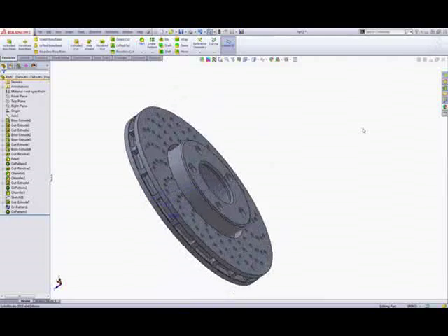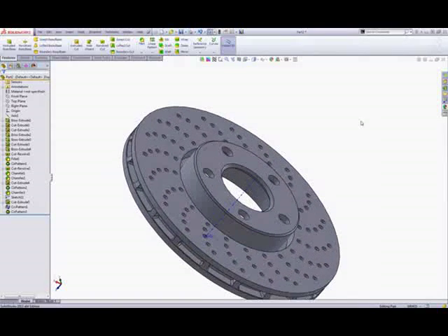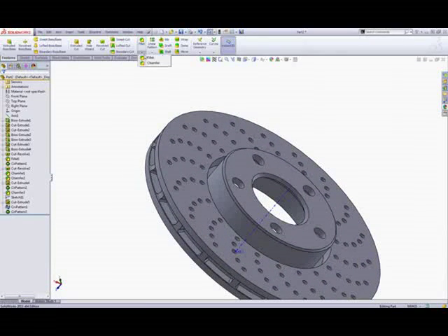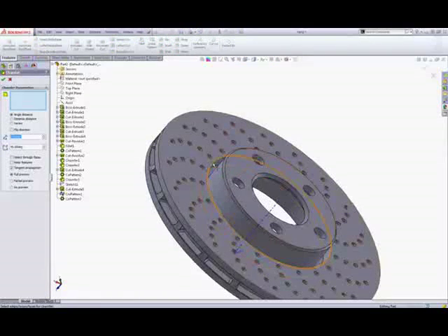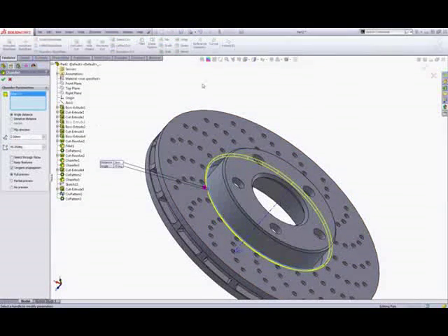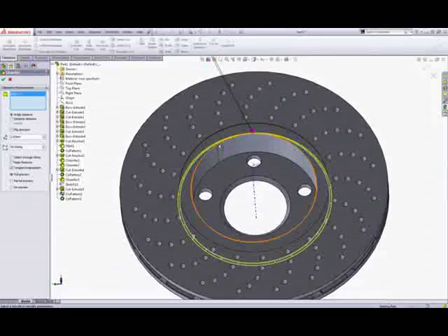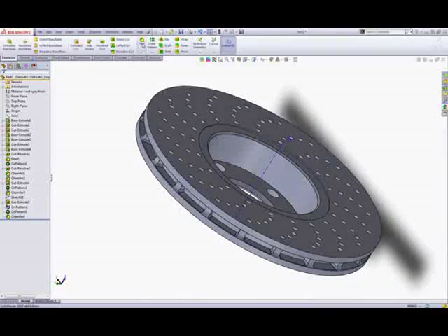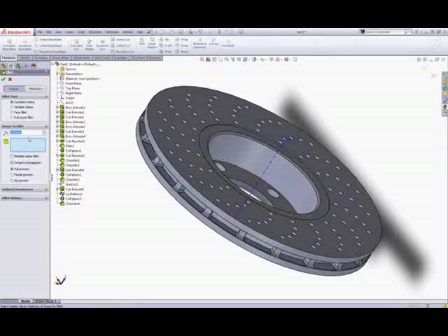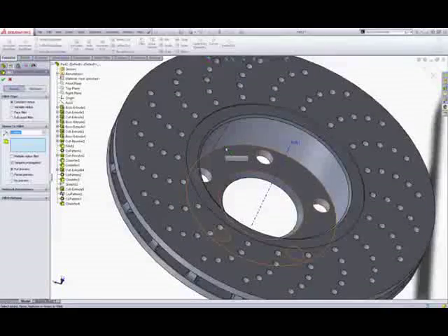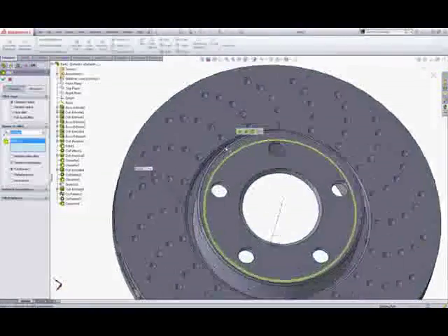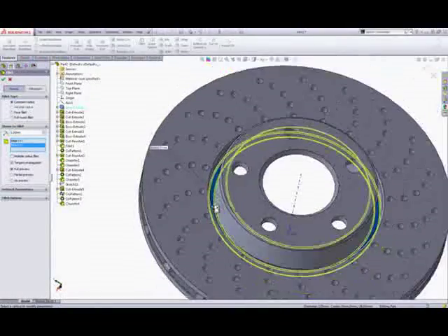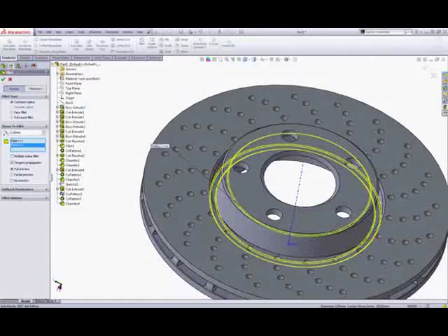Now all we need is to give it some fillets and some chamfers. You can start with some chamfers. Give this edge a chamfer of 2 millimeters and this edge also, and right click to accept. Choose the fillet tool and make it of 1 millimeter and choose this edge and this face and click OK to accept.